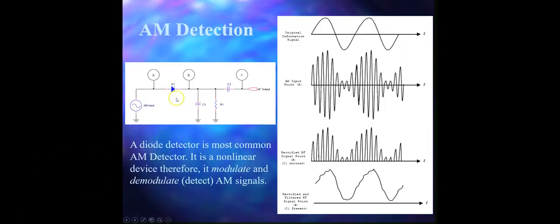The diode you see is a germanium type diode, and the use of this type of diode is common in AM detectors. A silicon diode usually requires around 0.7 volts of forward bias to conduct, whereas a germanium diode requires around 0.3 volts. This germanium diode increases the sensitivity of a receiver greatly.